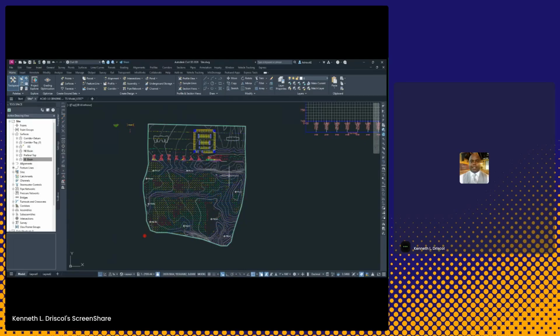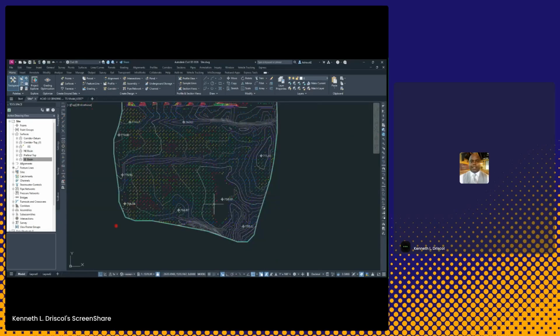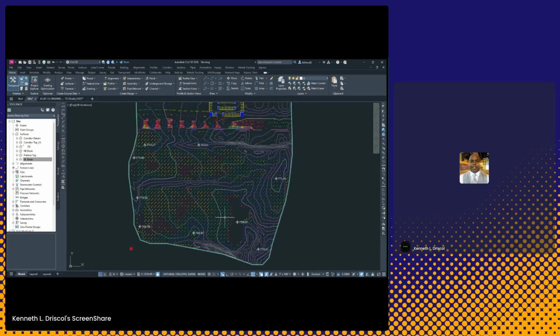And based upon that, of these overall slope arrows and these existing contours, I can see where rainfall and runoff flows. So for the most part, towards the south and to the east, where I might need my basins. So based upon the design parameters that they have given me for this site, I got these elevations, I got these standards that I need to meet in reference to my existing ground. I got some labels around here based upon the property line.